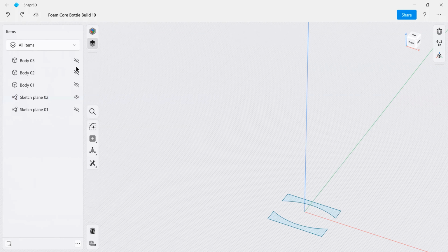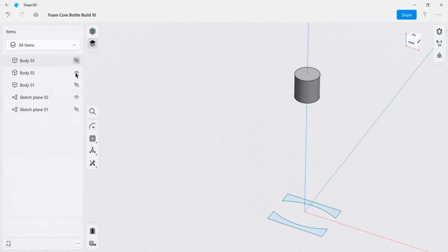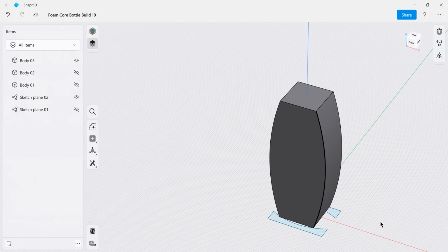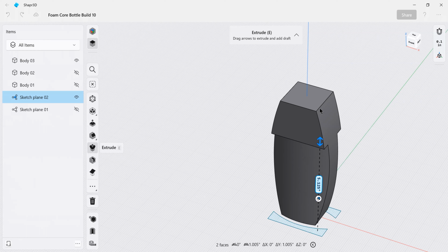Let's bring back that's my main body. Here we are. The closure, there we go. So now I can select these. When I have this mass, this body in position here, and then I select these two, and I extrude them up, with that other body in position, it's going to automatically separate those from this main body.